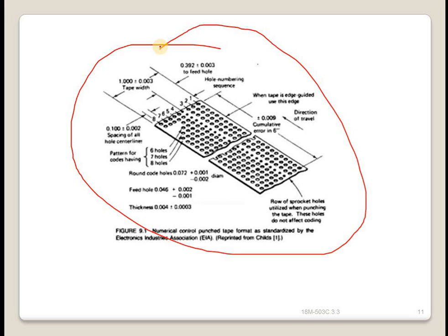Punched tape has been responsible for many of the important standards in the NC industry. The tape can be made out of several materials. Paper tape is common, and its cost is low. It is not durable and therefore not appropriate for repeated use. Stronger tape materials suitable for higher production use include mylar reinforced paper, mylar coated aluminum, and certain plastics.